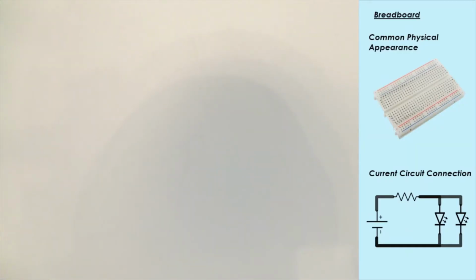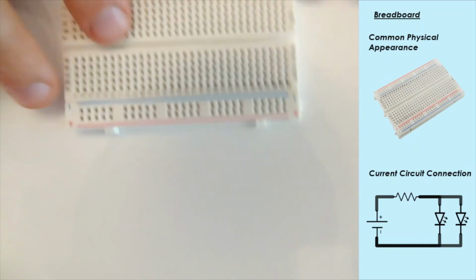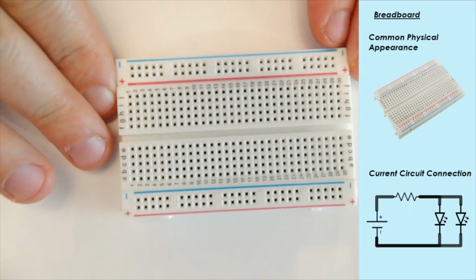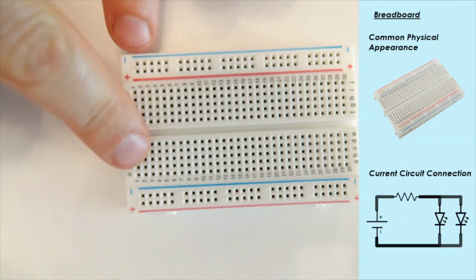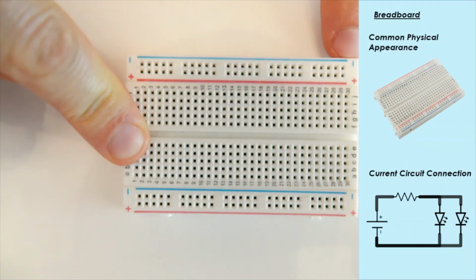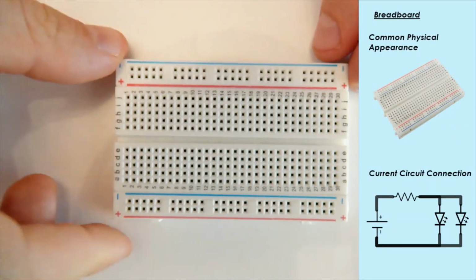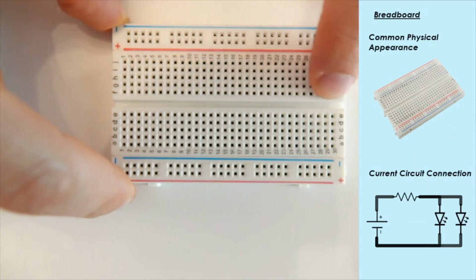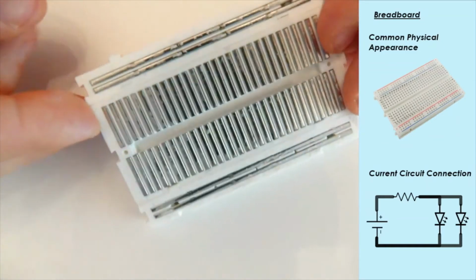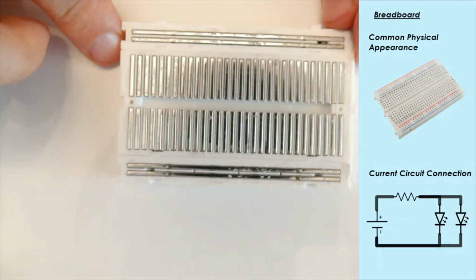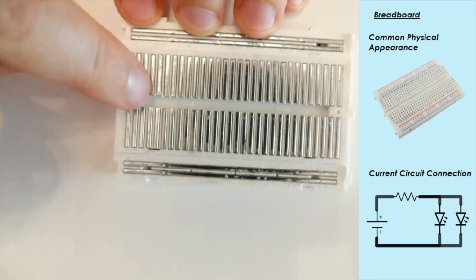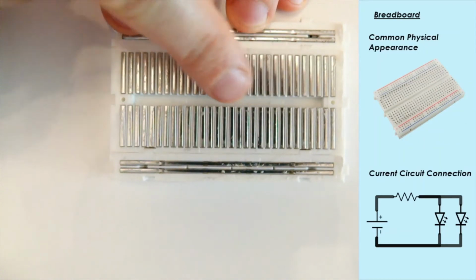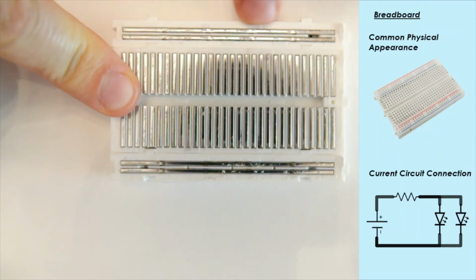Okay, so looking at a breadboard, what we have here is what we saw before. All of our rails connecting like so along here, and then our long negative marked with the blue negative color, and our positive rails here, and this breaker in the middle, this divide across the middle. We can easily see this because I've ripped off the backing of this breadboard. I wouldn't recommend it. And here you can see all of the conductive strips. So all of the strips going down, none of them connecting across that middle bit, and then the conducting strips along this long edge as well.